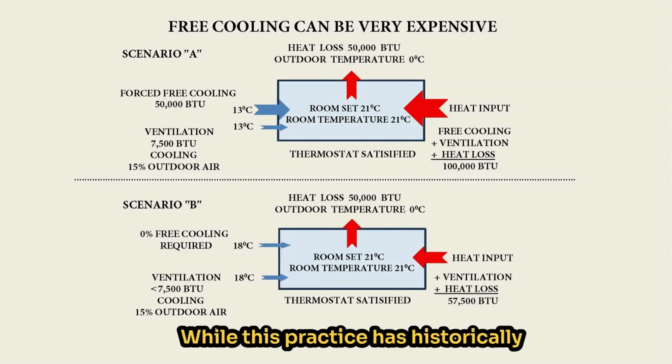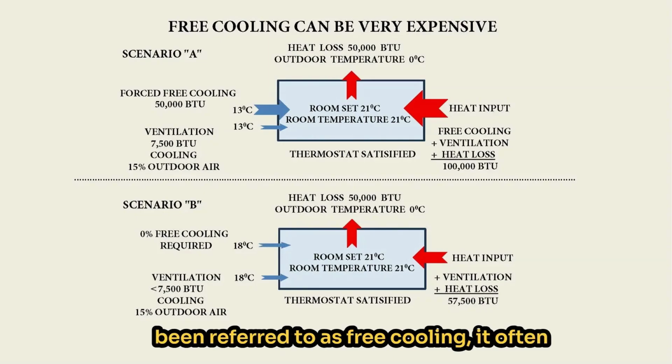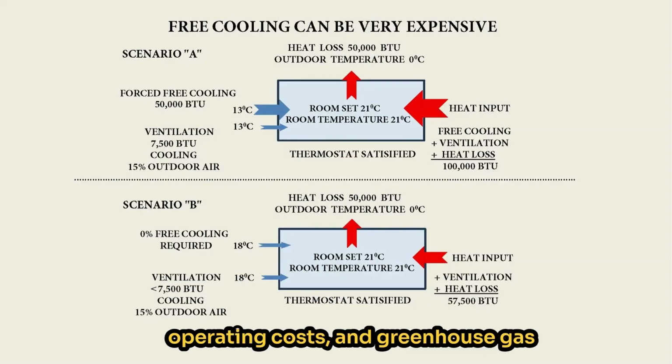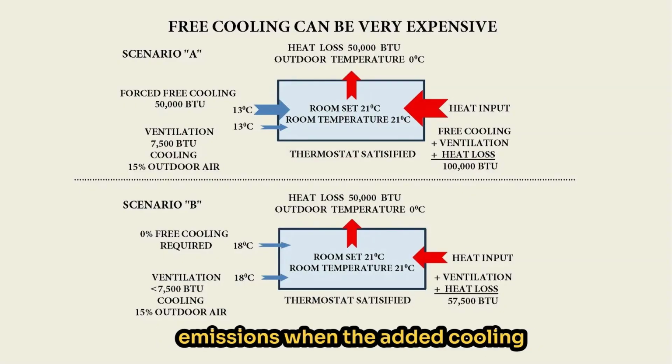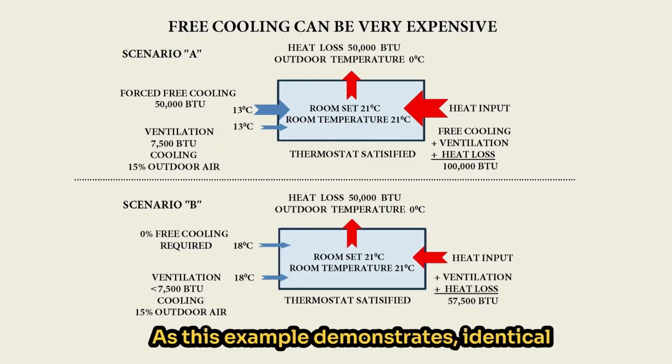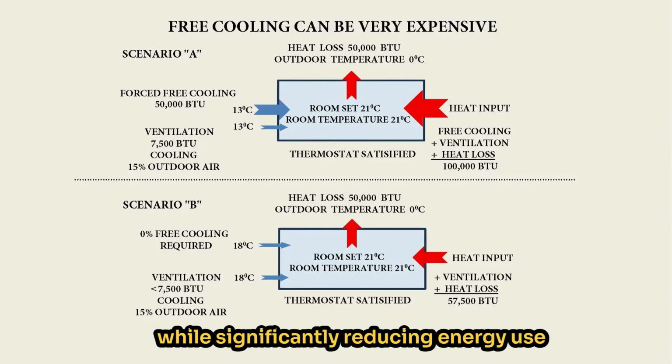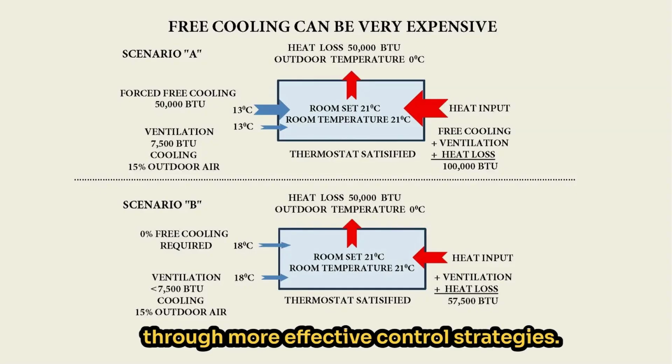While this practice has historically been referred to as free cooling, it often increases overall energy consumption, operating costs, and greenhouse gas emissions when the added cooling must subsequently be reheated. As this example demonstrates, identical indoor comfort can be maintained while significantly reducing energy use through more effective control strategies.